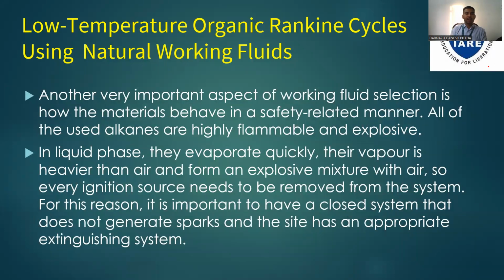Another very important aspect of working fluid selection is how the material behaves in a safety-related manner. All of the alkanes used are highly flammable. Propane, butane, pentane, heptane, and hexane are highly flammable, so we have to be careful with them. They evaporate quickly, and the vapor is heavier than air, so it forms an explosive mixture with air.